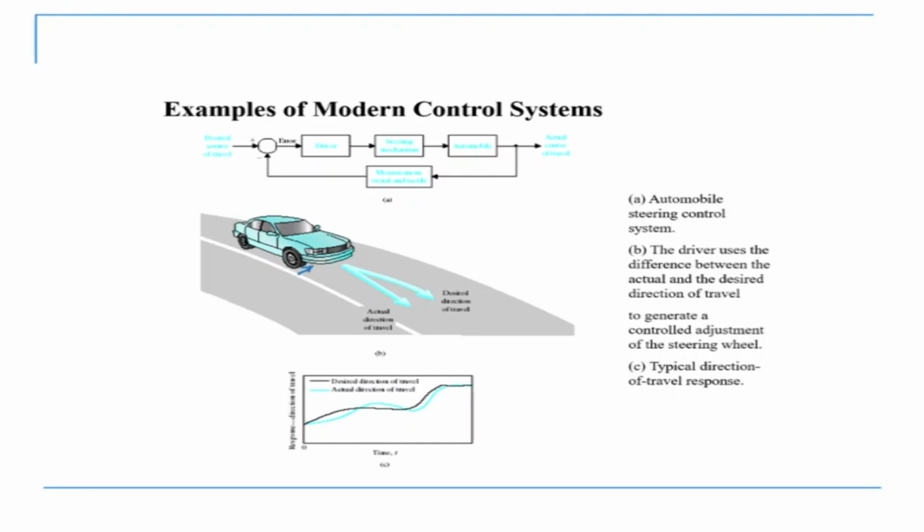So there will be sensors which will actually sense the position of the car. Maybe there is a camera or there is a LiDAR. So there can be LiDARs, okay, line lasers. So they will see what is the present position of the car in terms of its distance from the center line. If it has come too close to the line, it will push it away. So this is my distance. Here I'm saying the desired distance is being given as input. I want this car to follow this line and keep a distance of d, let's say 0.5 meters.